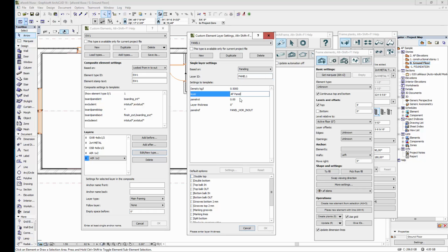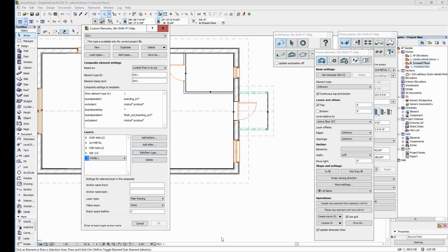It will go to the panel layer, it will be horizontal, and the thickness, now I need to copy, this is from the default settings, which is based on the metric, so thickness is 23 millimeters, which is about this in inches. And this is defined in the data folder. We will define the paneling profiles for you. And the layer type will be finishing exterior.